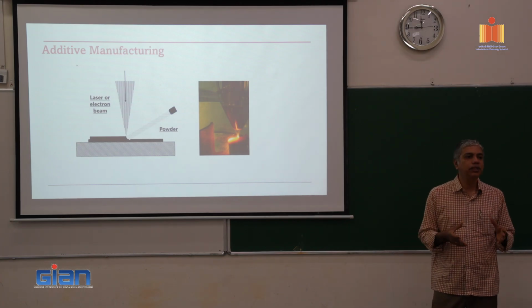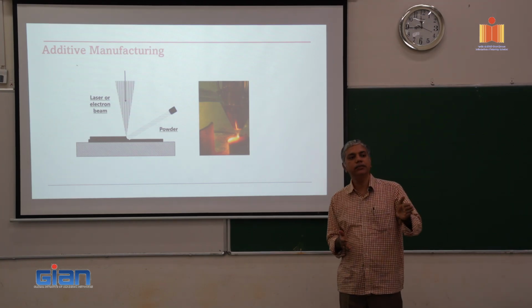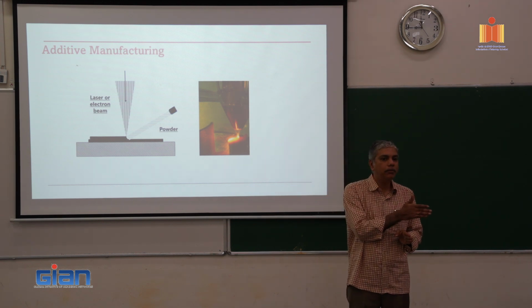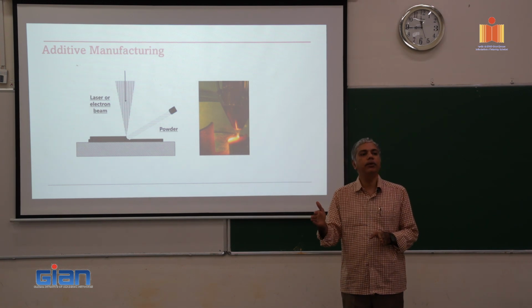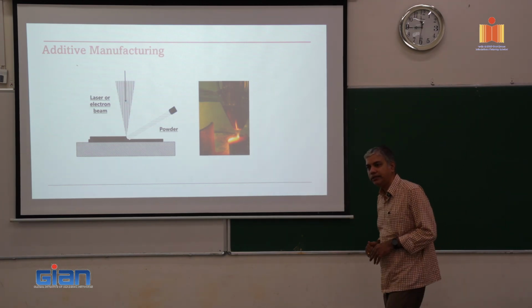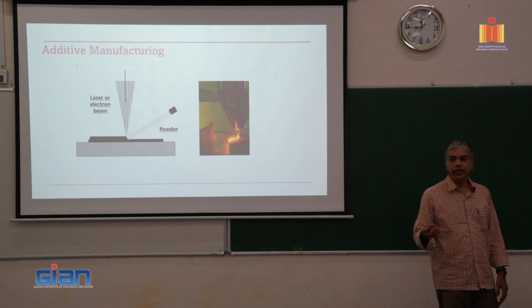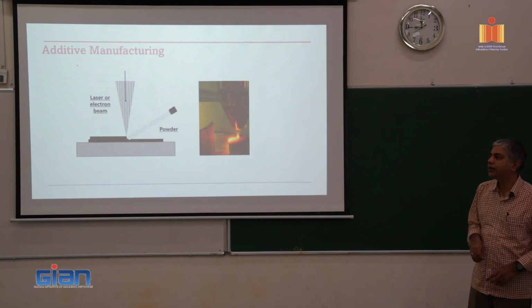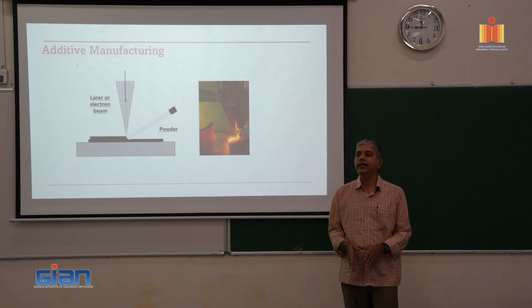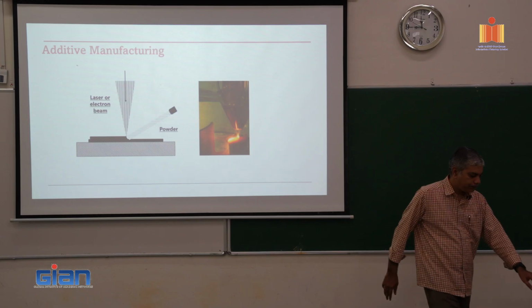It's not that it is impossible, but most of it is very difficult because the whole process assumes that you are spreading a thin layer of powder, where a blade will be able to move and spread the powder in an uninterrupted manner. That's not always the case in most applications, whereas DED, on the other hand, is usually more convenient. You can selectively add material where you are required. So DED applications are ideally suited for repair applications in the additive manufacturing segment.